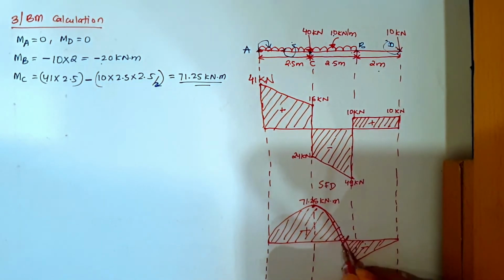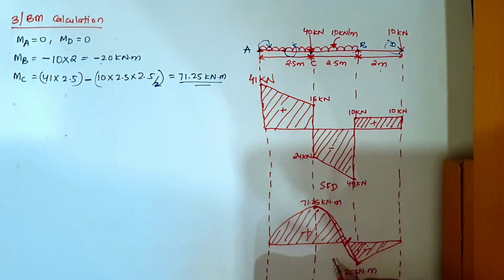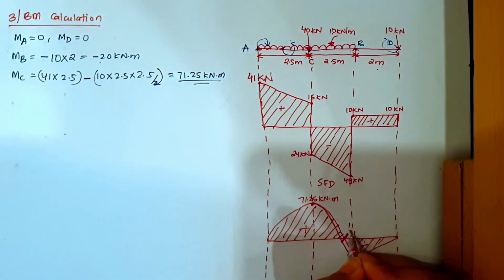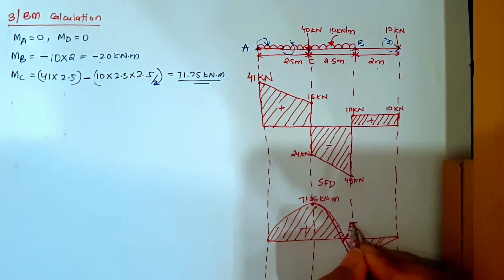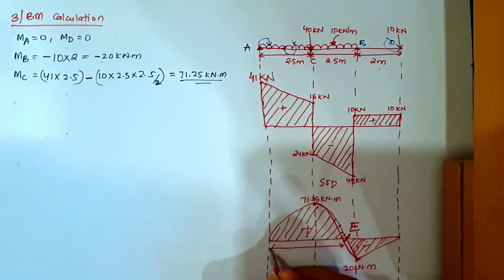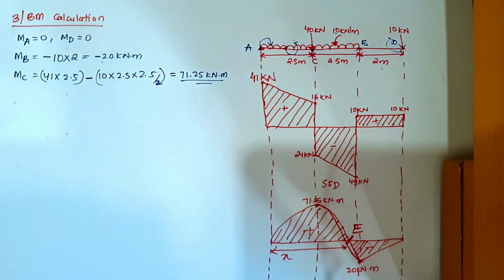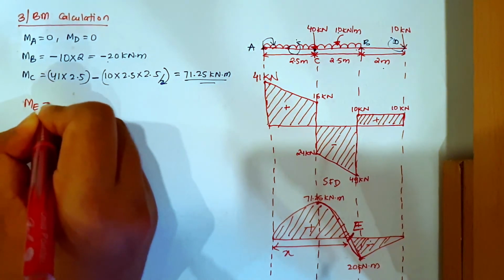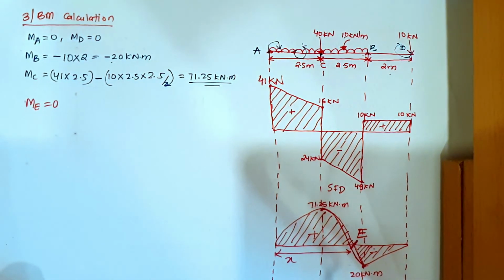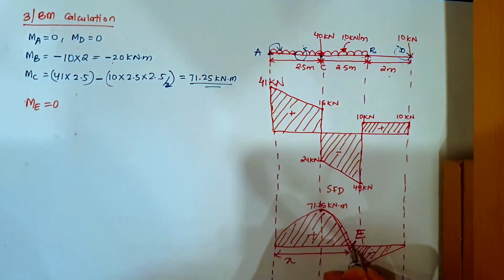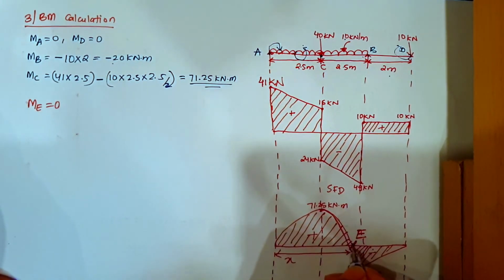Okay, now this point here, ये point पे the moment is suddenly changing from positive to negative. So this is a point of Contra flexure, and let us name this point as point E. Okay, now how do we find? We need to find this distance कि कितना distance पे point of Contra flexure occur हो रहा है. So how do we find? We find it by equation moment at E is equals to 0. Right, so how will we find here? We need to come from, if I draw a fringe line again, मैं यहाँ से ऊपर लेके जाती हूँ.